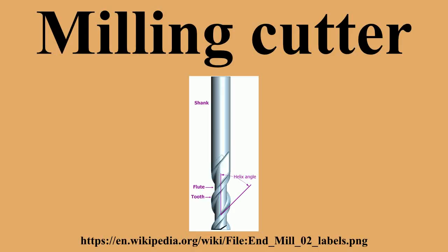They are sometimes called ball mills in shop floor slang, despite the fact that the term also has another meaning. They are also used to add a radius between perpendicular faces to reduce stress concentrations. There is also a term bullnose cutter, which refers to a cutter having a corner radius that is fairly large, although less than the spherical radius of a ball mill.